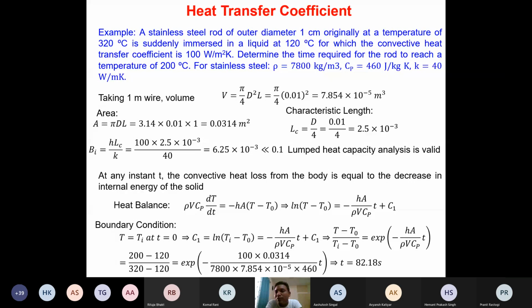If it is occurring from the radial direction, we in general take the radius or the diameter as the length, isn't it? If we are looking at the heat transfer in the axial direction, we take the length of the pipe, isn't it? But in this case, both are occurring. So which length should one select in such cases? In such a case, we look at the characteristic length, which is nothing but the volume by area. You understand why this characteristic length, volume by area, is used?